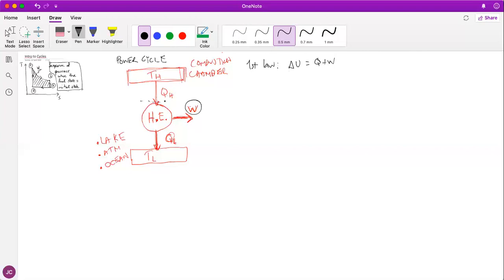Notice this: I'm doing the analysis for this heat engine, and this heat engine can be as complicated or sophisticated as you want, but you don't have mass flows into or out of it. You just see energy transfer as work or as heat, okay? Therefore, that's why I'm putting it for a closed system. It's not an open system, okay?